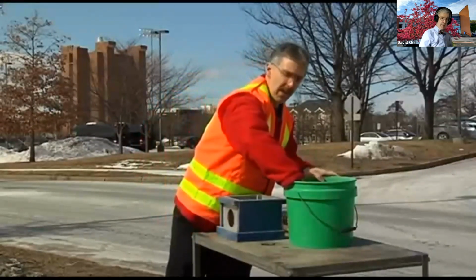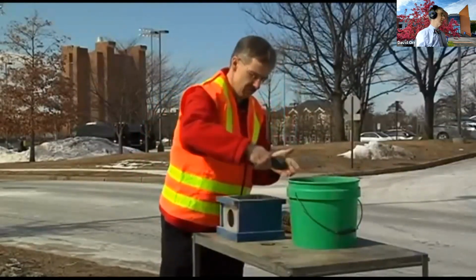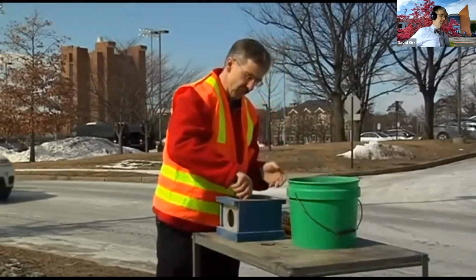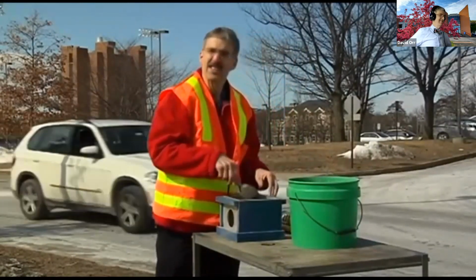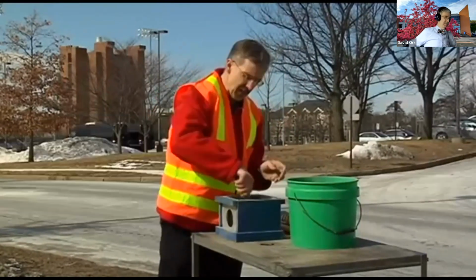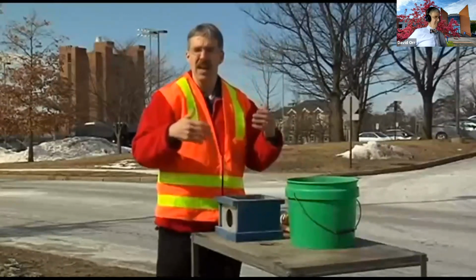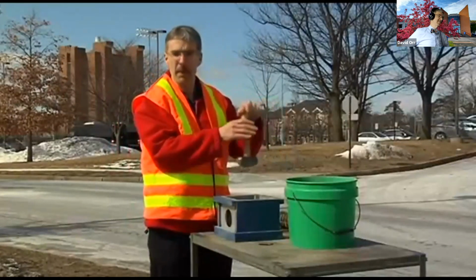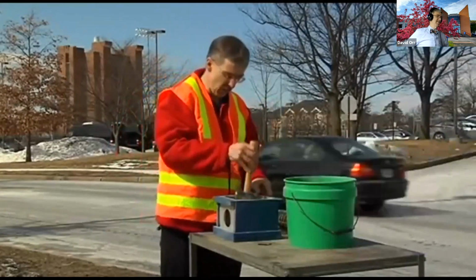So now we're going to put some gravel into our bed. In the field, normally we'd be putting how thick? Well, 6 inches. Thinner is better. Too thick, and you can't get compaction. Too thin, and it just takes you too long. So normal rule of thumb is about 6 inches. Here we're going to be putting just very thin lifts because it's a demo.